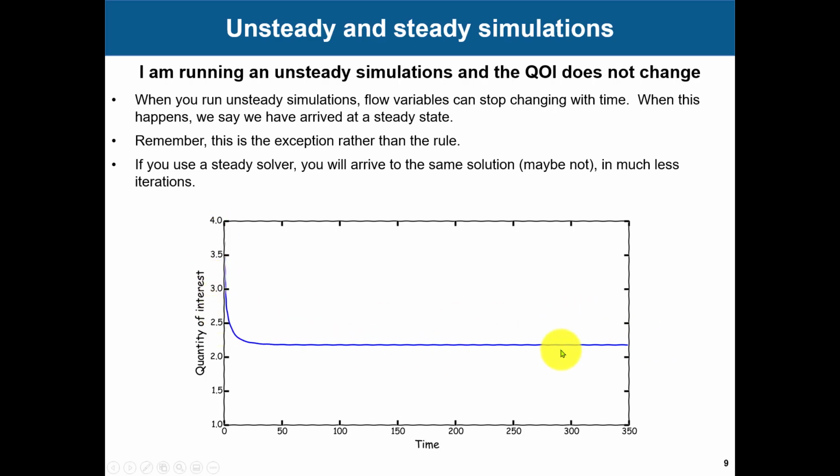Okay, so these are typical behaviors of steady solutions, when you see that your quantity of interest is not oscillating anymore for long times. Sometimes you can have them settle at later times. Sometimes also what you can do is force-add a perturbation in the flow to set an instability. If that instability is damped fast, you know that it is steady.